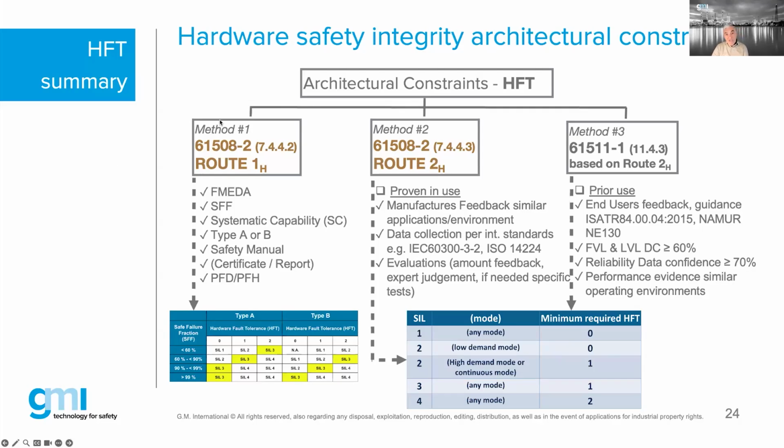So when I look here at this theory approach, which is the one over here, when a manufacturer starts a new product from scratch, I can tell you those developers are using the 61508 as a guidance. And if it is a pure hardware device, like a safety relay with no firmware or software in there, then mainly they will use this table 2, and they will look into part number 2, which is called the hardware section from the IEC 61508.